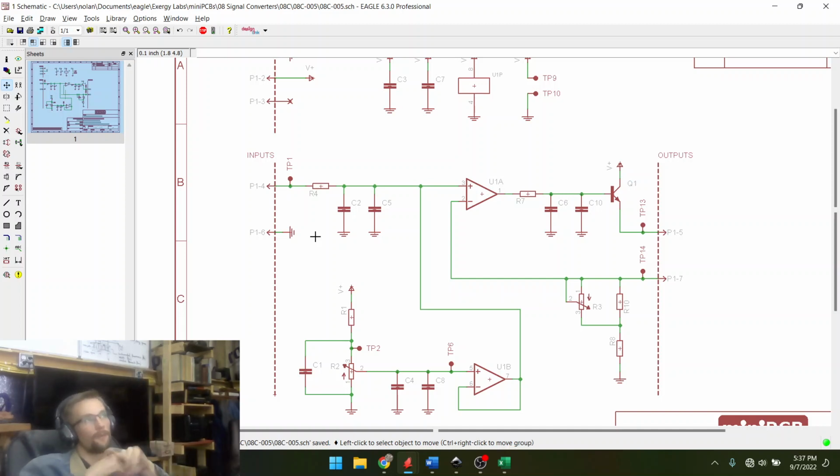So it's the reference, the ref negative input, or the in negative, which connects to ground, but since it's not the return path for the voltage source, like the V+, it shouldn't have noise on it.